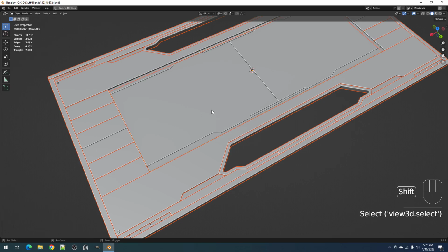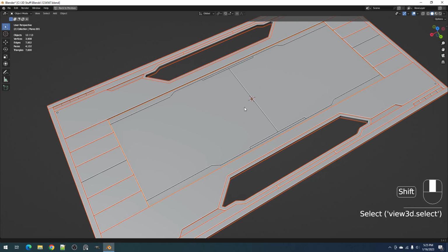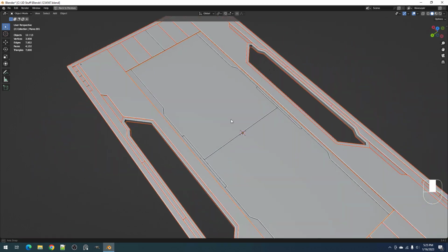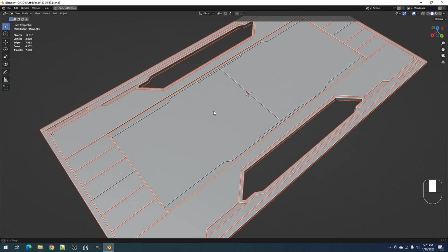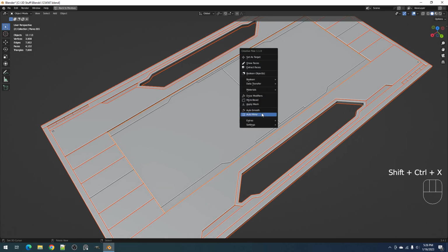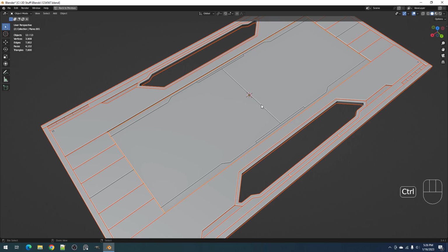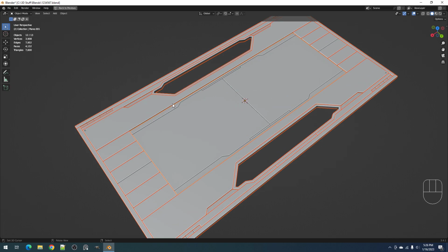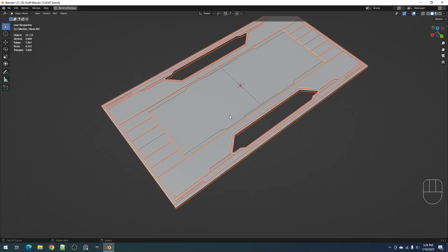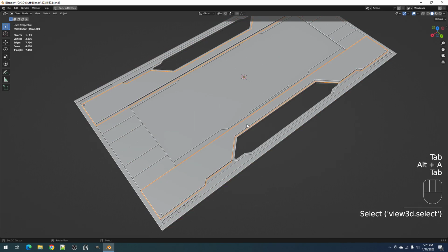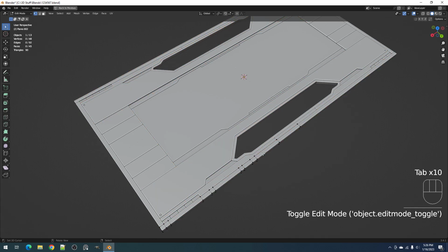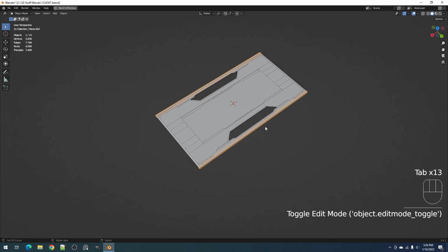We're going to make the object that is mostly at the center part of the selection be the one that's going to supply the auto mirror coordinates. So we're going to mirror this part, and it will also be reflected with the other selected objects. Auto mirror XY. Here we go. Now you can see that. So it's a pretty convenient method of mirroring.